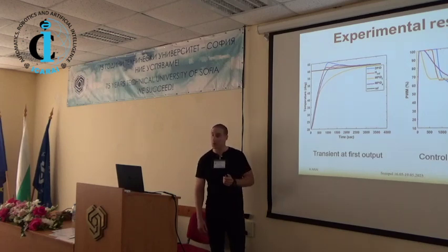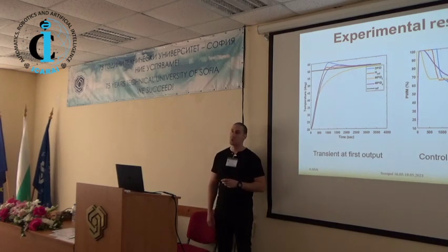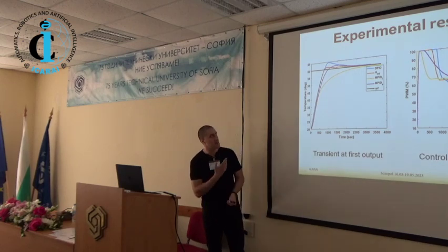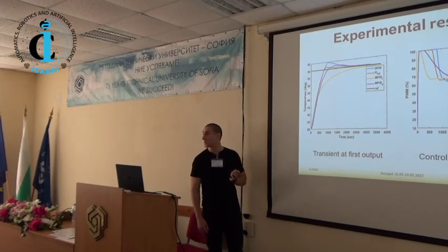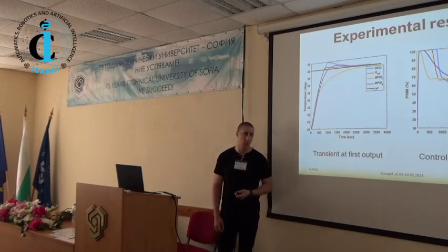We tuned an additional controller based only on the information for the steady state, and then through auto-tune procedures designed a decentralized PID control with use of the decoupling matrix. And these are some of the comparisons. As we could see, the full-order H-infinity controller, in our case, gives the best results, but the slower multivariable PID controller with the purple line and the decoupling PID have some comparable performances.